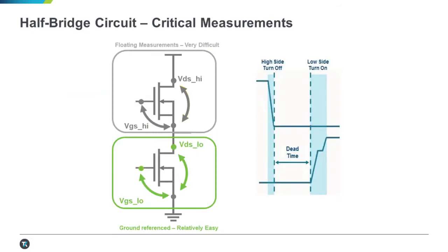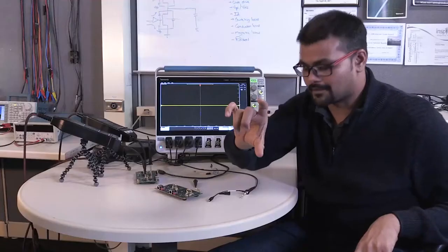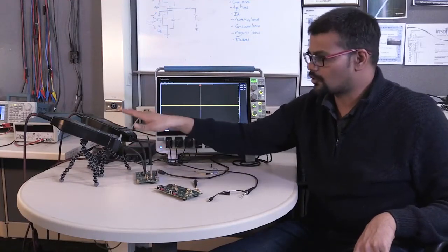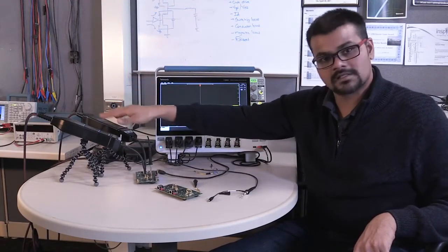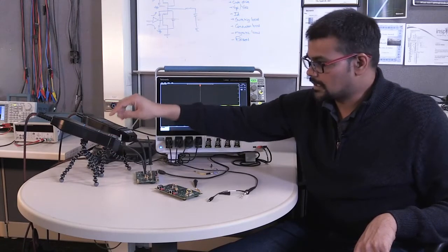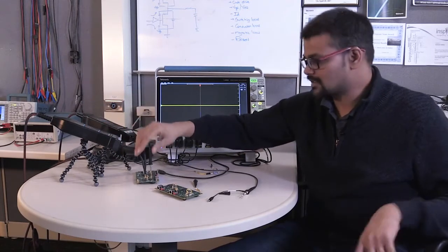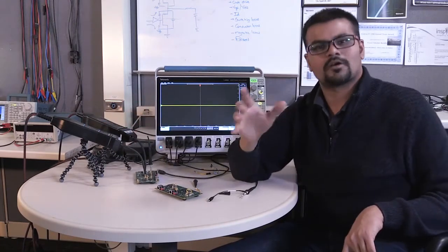So half bridge, right? You have the ground level signals, all good. You can do that with passive probes usually, right? But the high side, you're switching really fast and you need a differential measurement, right? So you need to reject all the common mode you can at a very, very high bandwidth, right? That's where this comes in. So these probes are rated for 1 gigahertz and 800 megahertz respectively, 2500 volts for silicon carbide designs, and then 50 volts for smaller GaN products, right?